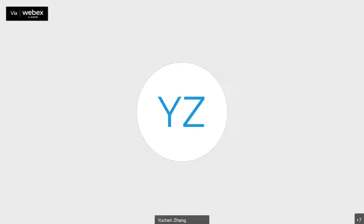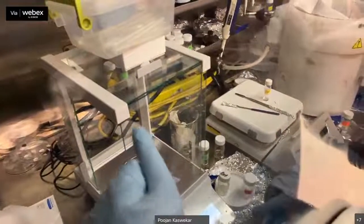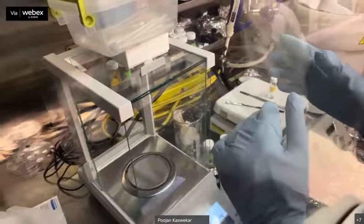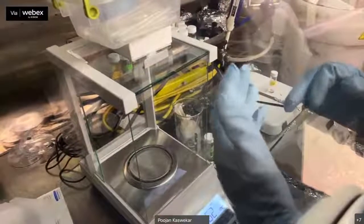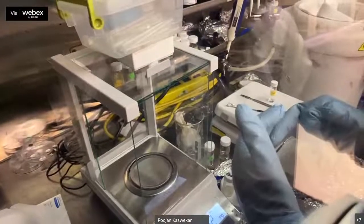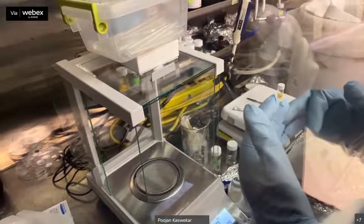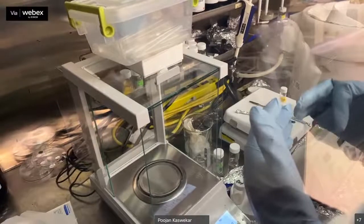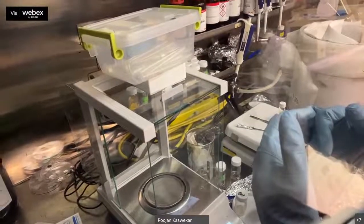I guess you can hear me and see me as well. Here we are preparing the solutions for perovskite. Normally we do 3 kinds of fabrication. We are trying to fabricate a tandem device. The tandem device basically consists of 3 band gaps. One is the low band gap, which is 1.12 electron volts, the second is the medium band gap, which is 1.5 electron volts, and the third is the large band gap, 1.8 to 1.9 electron volts.